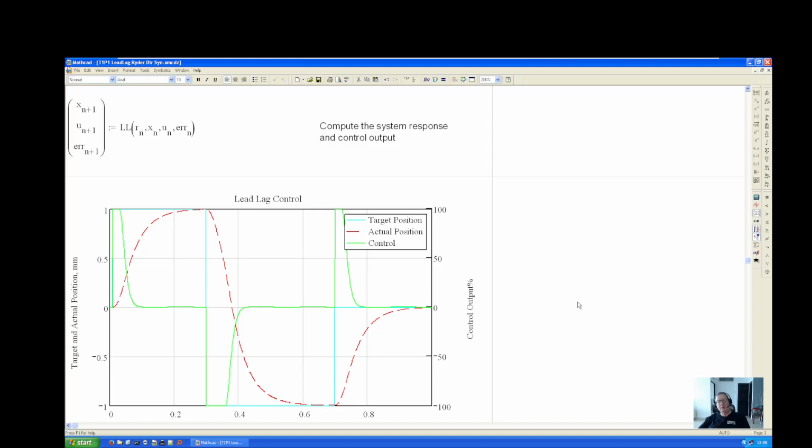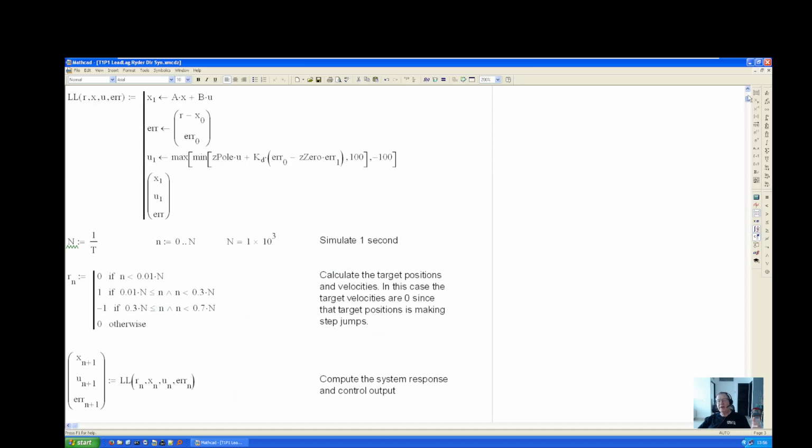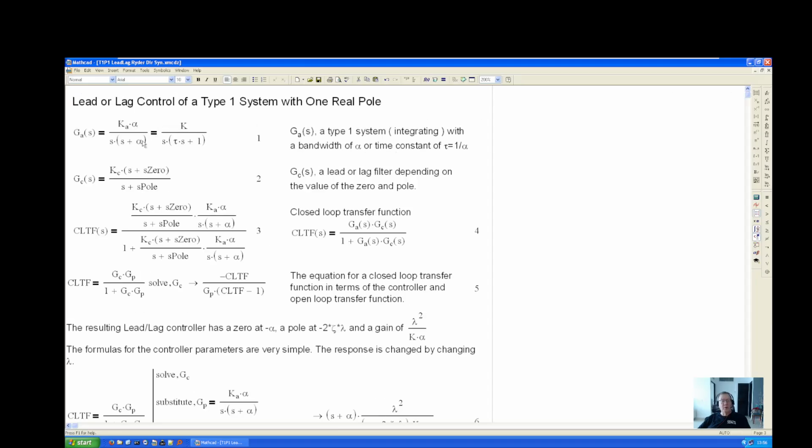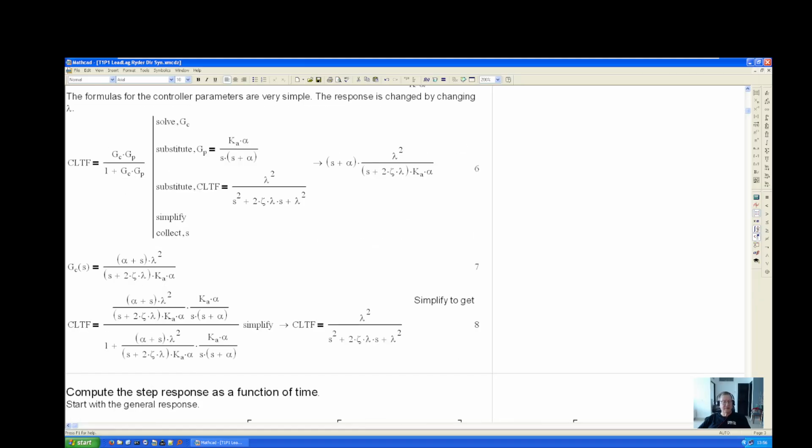So that's what's wrong with a lot of these videos, is they don't take into account there's a difference between the controller and the open loop system, and there's a limit on the 100% output. So if you don't have the system designed right, in other words, if I wanted to go faster, I would need to increase K from say 1/4 to 1, and then I would be able to go faster. But right now, my open loop transfer function or gain is only 1/4 of a millimeter per second per percent output.